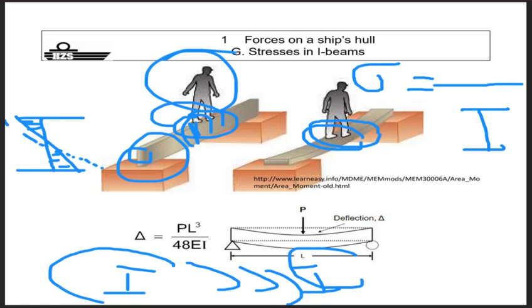The bending moments that take place here or here or here depend on the local internal bending moments. The reaction forces due to the external one are linked to one another. So if you have the external one, you can calculate the internal one. So your stress level will be dependent on what? The bending moment exposed to at that certain spot.